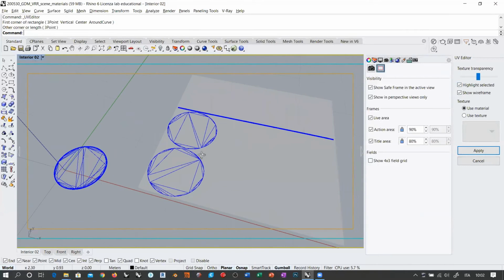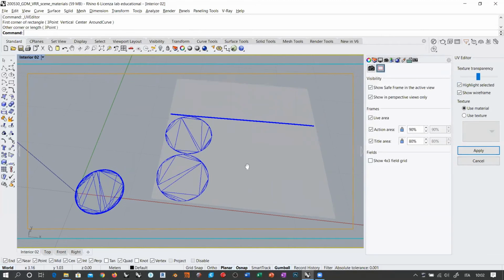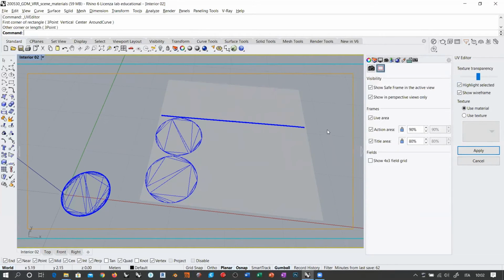So we got to probably one of the main aspects of rendering. The objects that you render in Rhino, even if you are working in Rhino, which is a NURBS modeler, are meshes. And so what you see here is the actual mesh representation of your table, unwrapped and unrolled on the plane, okay, on the XY plane. So the show wireframe is not showing the actual wireframe of the NURBS object, but the wireframe of your mesh object. And this mesh object is created automatically.